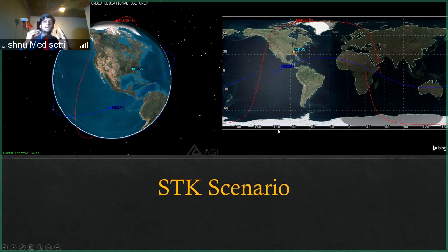So we can input our new orbital parameters. Every time a satellite passes overhead, we have its last known location, right? And we take that location data and we can put it into STK for it to recalculate the new trajectory of the satellite. And it can do this in a variety of different methods, including a very simple 2-body assumption, all the way up to accounting for different perturbations like the J2 perturbation. And so this allows us to get the most accurate representation of where our satellite is located at any moment.